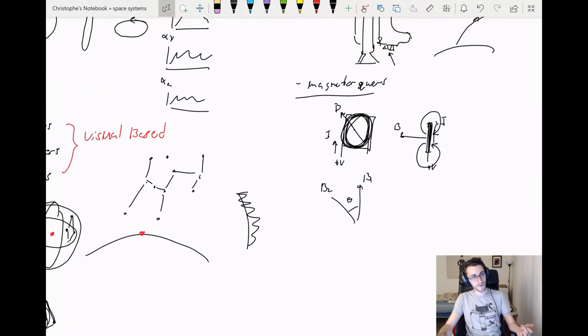And the same goes for magnetic fields generated by the Earth and magnetic fields generated by the magnetorquers. So as your spacecraft is moving through its orbit, if you've got your magnetorquer powered, it'll apply some force to try and align itself with the direction of the Earth's magnetic field while you're in orbit.